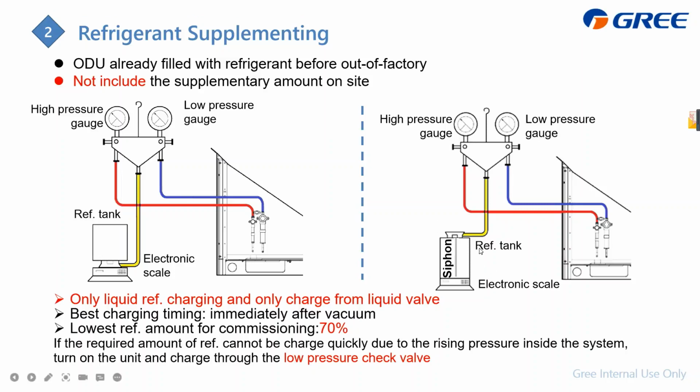And if this refrigerant tank has a siphon in it, we do not need to reverse it, just like this. Upright is okay.